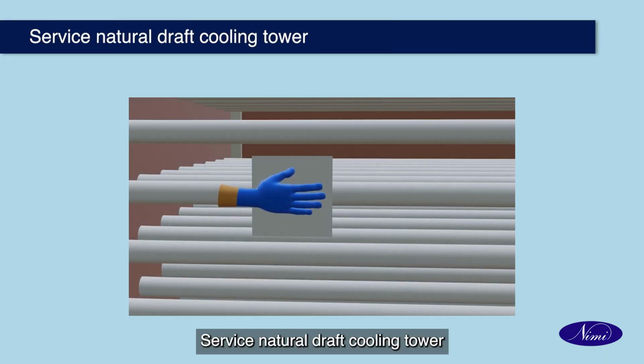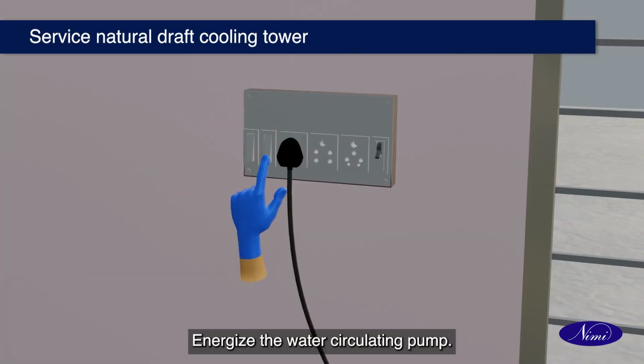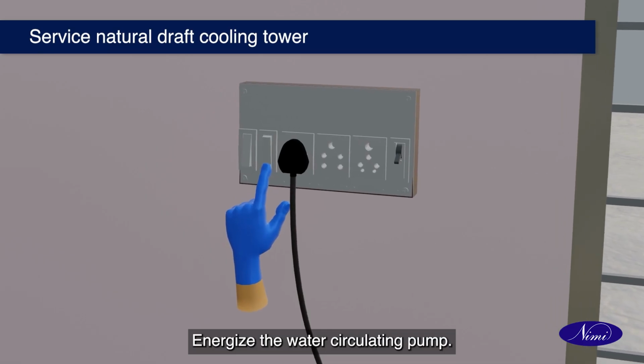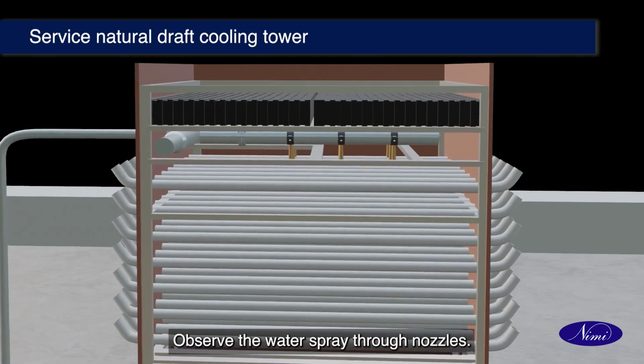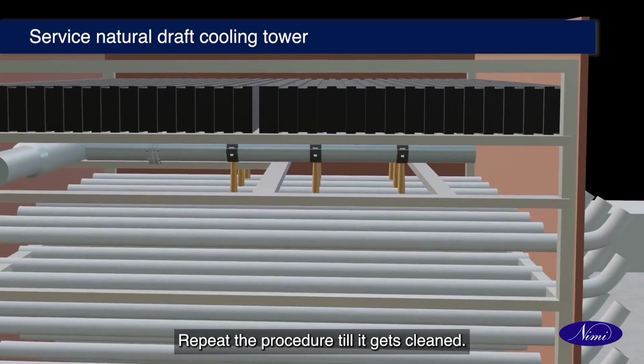Service natural draft cooling tower. Check the water spray. Open the inlet and outlet valve. Energize the water circulating pump. Observe the water spray through nozzles. Repeat the procedure till it gets cleaned.